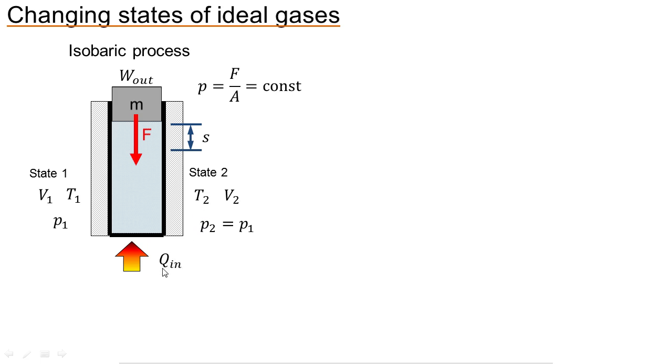It has a higher temperature, and it has a bigger volume, you can see here, but the pressure stays the same, because the pressure is not determined by the heat, it's determined by the gravity and the mass m, and this will stay the same. I can calculate the new state of this gas with the volume, temperature and the pressure with these formulas here. You might already know them, they are very common in thermodynamics, these are the easy ones.